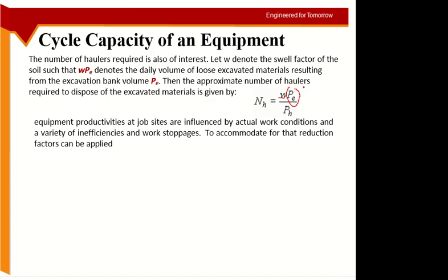These are theoretical equations, but you have to keep in mind that practical work may not be that ideal. The work conditions may not be ideal. People will need breaks, there could be problems with the site, there could be problems with the equipment. You may need to stop on a trip to refill the fuel and so on. So some of these things should be taken into account, and you may use some factor of safety.